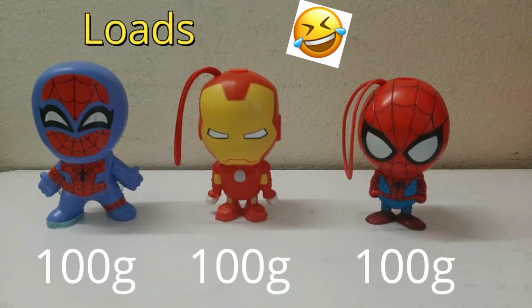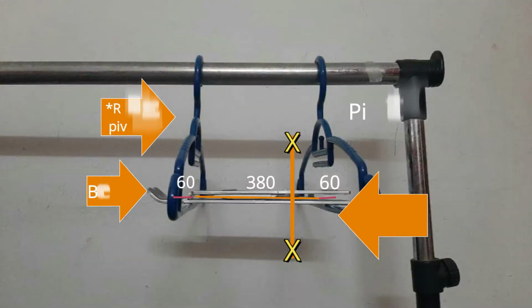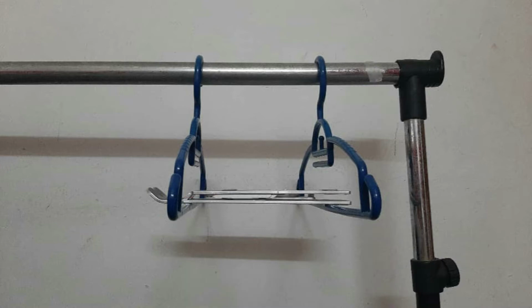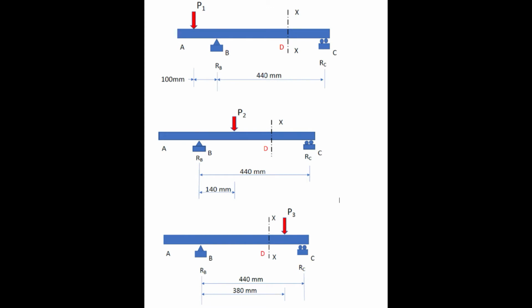Three loads of 100 gram each are prepared as in the diagram. For simulation purpose, we use hangers as the pivots, a metal acts as the beam, and digital meter display is given data values. The loads are placed at 3 positions as shown in the diagram. There are 3 cases in total. P1 100 mm left from B, P2 140 mm, and P3 330 mm, both at the right of support B.